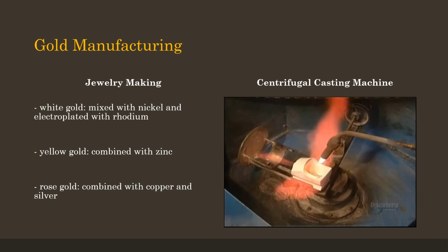Once the wax replica is finished, it is attached to a wax stem and then encased in a small container filled with plaster. The container is placed in a vacuum chamber to make sure that no air bubbles will form on the inside, as any air can cause imperfections during casting. The container is then placed in a furnace to allow the wax ring sample to melt, and the wax stem also acts as a channel for the gold to flow into.